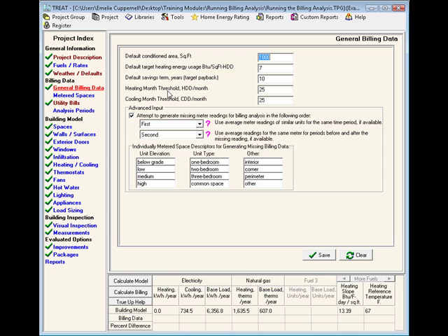Using the entered bills and the weather site, Treat calculates a heating degree day per month for each bill. If that value is below the threshold, that bill will be considered baseline only. This value depends on the building heat loss rate, reference temperature, and specifics of the heating system control.